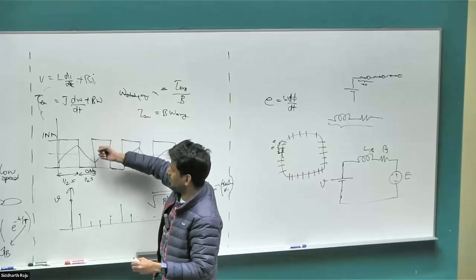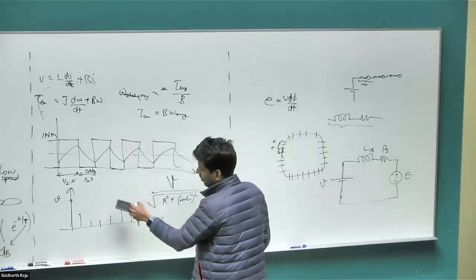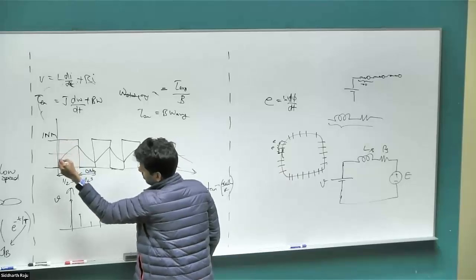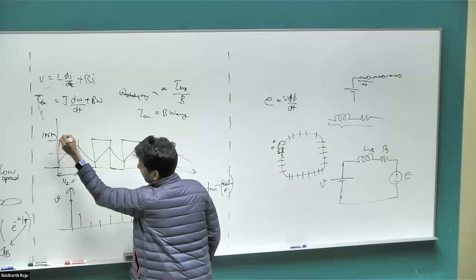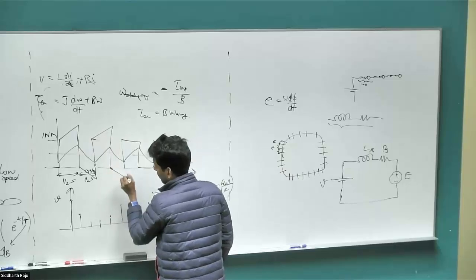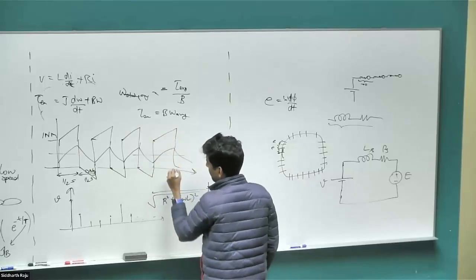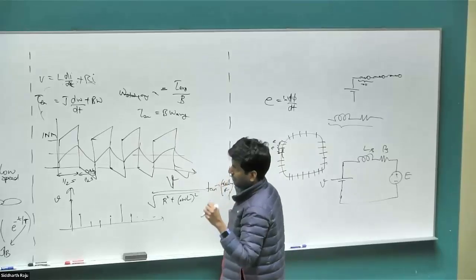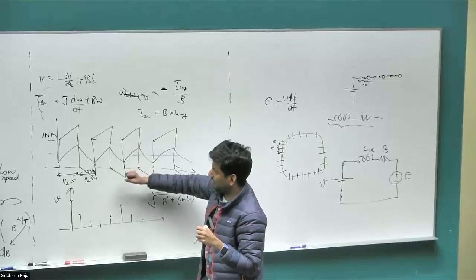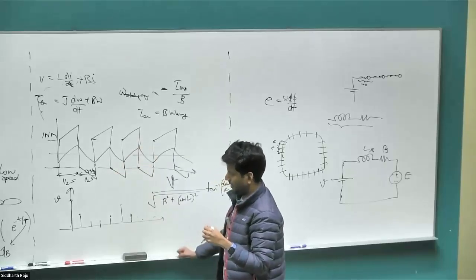Just because it's a different equation, that doesn't mean we can't use a method of solving that we have learned already. Right? And the nice thing about going with Fourier is I can have more and more complicated models as well, which might get too complicated to solve using Laplace. So I can have a waveform like this, and then this can go up like this, go down like this, go up like this. This would get a little bit tricky to solve with Laplace. Not too hard. You can still apply superposition and decompose it into a triangle and a step waveform. Just because it's a linear circuit, you are good with doing that. And in this case, you can still solve it, but it would be much easier to just get the Fourier series of all these kinds of signals and solve it straightforward.